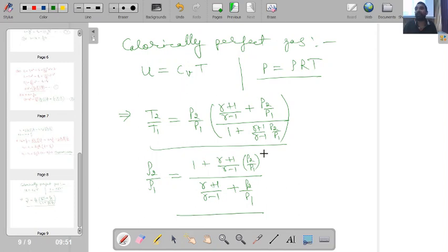and we have represented all the properties as the function of upstream Mach number. But in the present analysis, because our fluid medium is stagnant, the flow velocity is equal to 0. That is the reason, and we are having a moving shock wave. For most of the cases, if we have to characterize the strength of the moving shock wave, the ratio of pressures is an important tool. The ratio of pressures is considered an important parameter which gives us information about the strength of the shock wave.